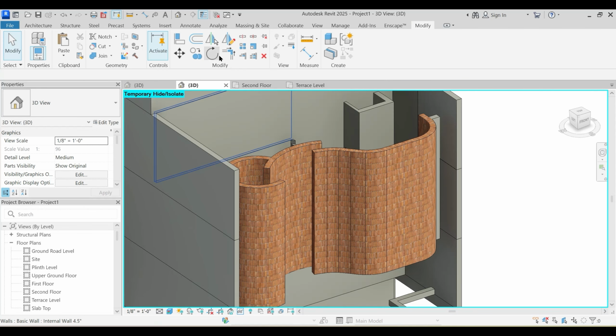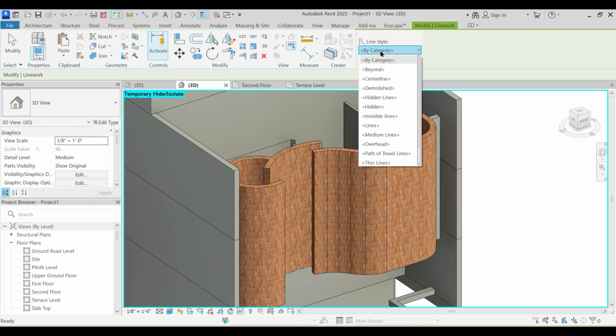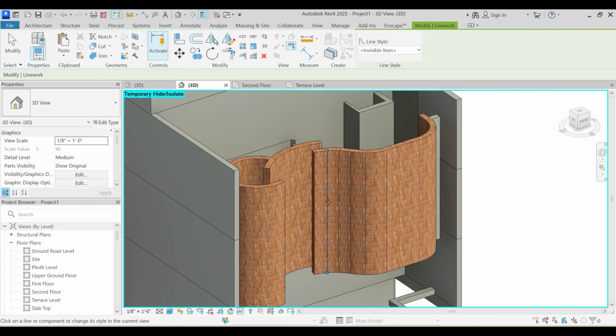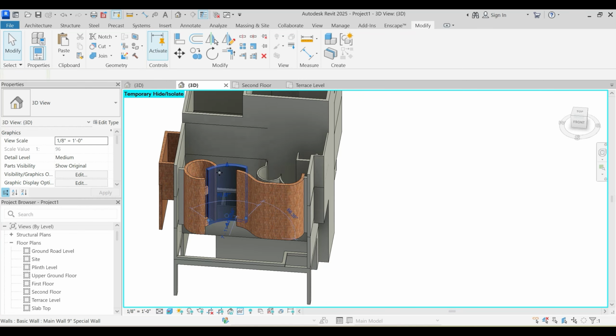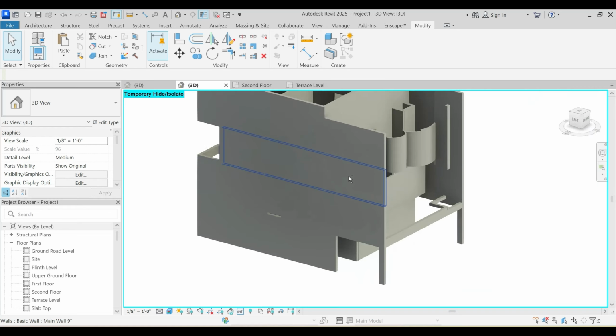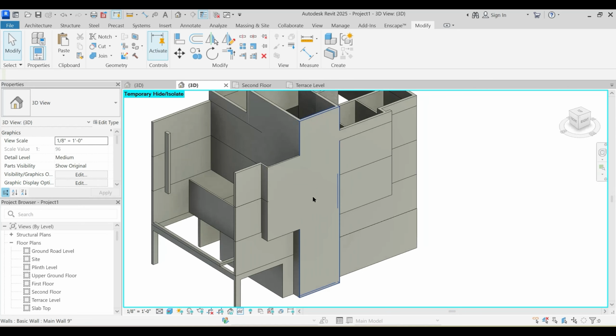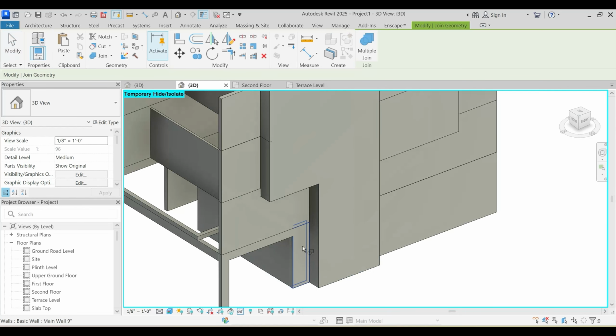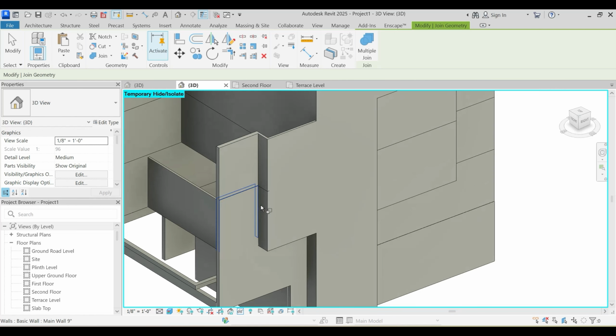Also this, I need to go to line work and say invisible lines and double click this and just get rid of these construction lines. Okay, and with this, select all these walls also and H. Then what remains is this particular main wall, of which you can just go to join all the walls in order to have one uniform surface.